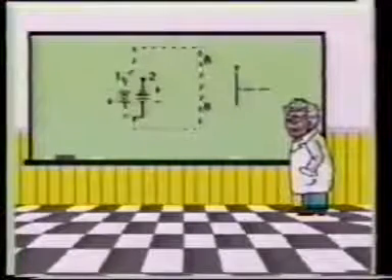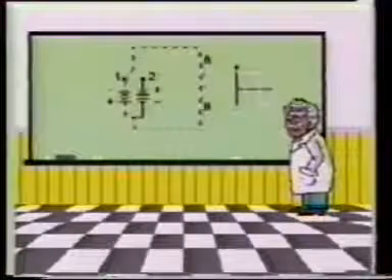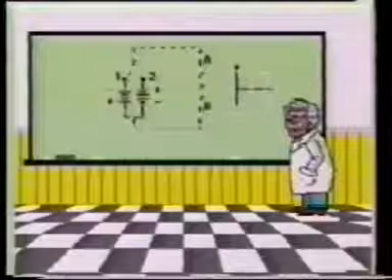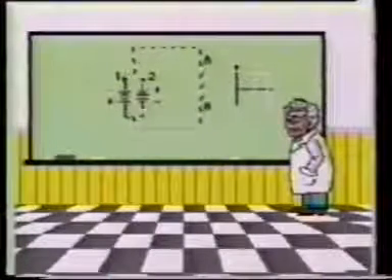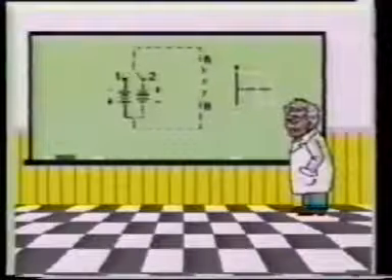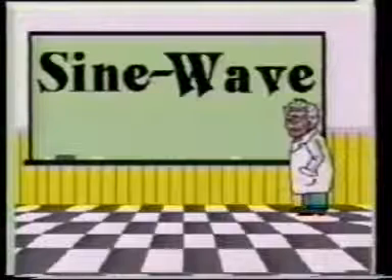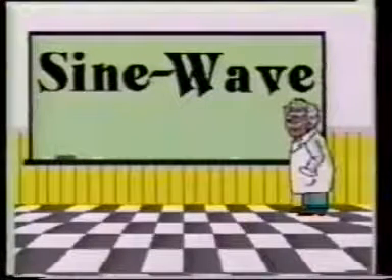If we continue throwing the switch from position 1 to position 2 and then from 2 to 1 at 1 second intervals, there will be an alternating voltage across the load resistor. The current flowing through the load resistor will be reversing itself at 1 second intervals. The AC circuit we have just described is a very simple one, and the AC voltage which is generated commercially is considerably different. The most common type of AC wave and the type most practical to generate is called a sine wave.